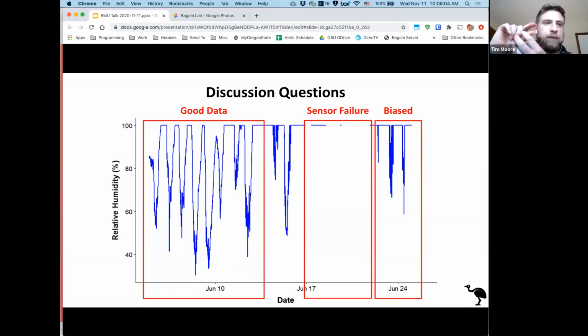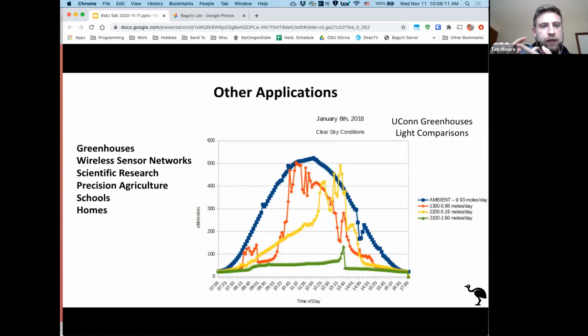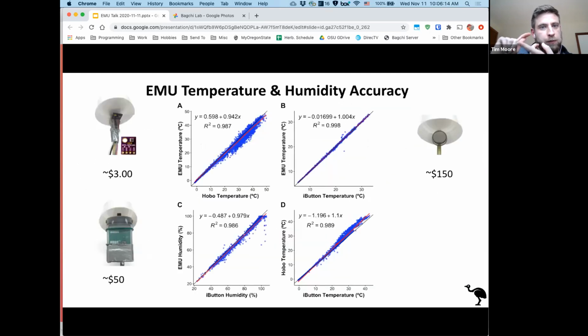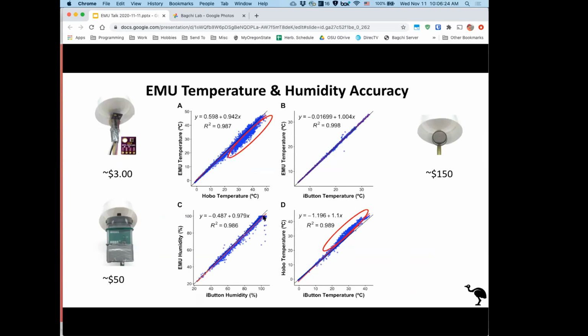And so you can imagine in that little sensor that has a tiny little hole allowing air into it in order to measure humidity, the conditions could arise where you're actually allowing that air to get supersaturated. So that's potentially why you're getting those readings over 100%. Yeah, so that's this slide right here. These are readings over 100%.